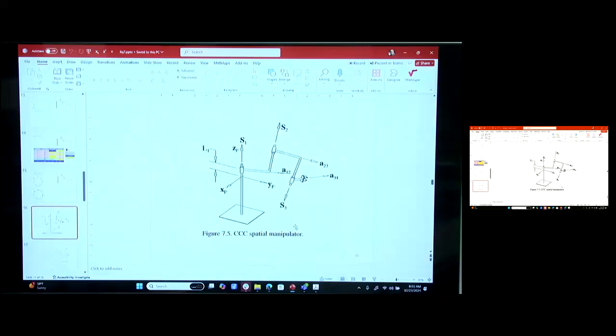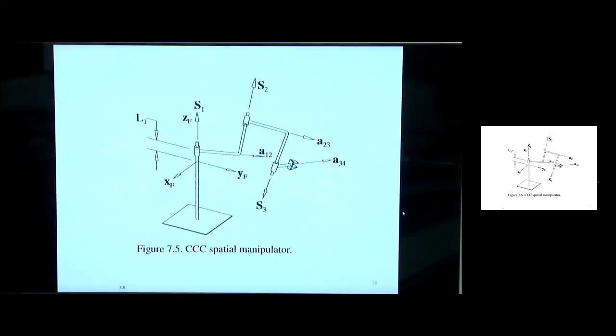So I wanted to do a reverse analysis, and I said, oh, this is going to be the simplest mechanism. Because basically the equivalent spherical mechanism when you close the loop is just going to be a 4-bar. So right, we're going to have like Z41 equals C23, you know, Z. So I said, oh, I just want something easy.